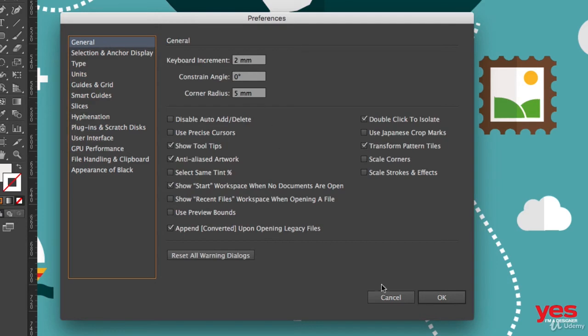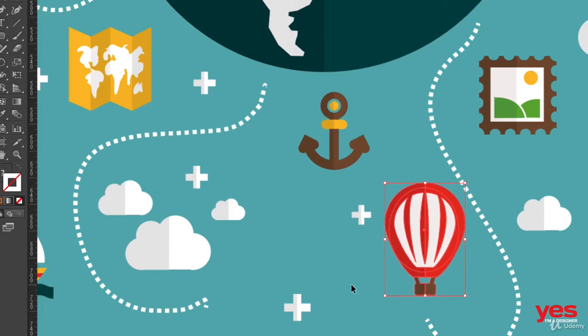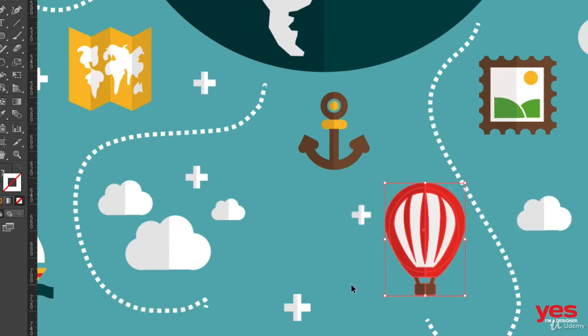Now what does that mean? If I click OK and I select an object like this balloon, I can use the arrow keys on my keyboard to nudge this object around, left and right arrows or up and down arrows like that. And each time it will move 2 millimeters. If I hold down the shift key, I can nudge by 10 steps at the same time. So that will mean, in my case, 20 millimeters each time I press an arrow while holding down the shift key. This is extremely useful when you want to just nudge things around.